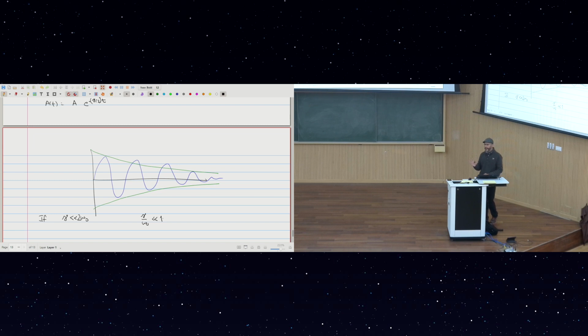These are situations where you ideally do not want any damping. You want the system to sustain itself, but nature does not agree with that, so there will be some damping. So you try to design the system so that the damping is very small. You reduce the friction, you put oil, whatever you want to do, you just try to keep this number very small. We have those situations where damping is undesirable, so we try to minimize it. This is another special case out of that bigger case of underdamped. This is called lightly damped.